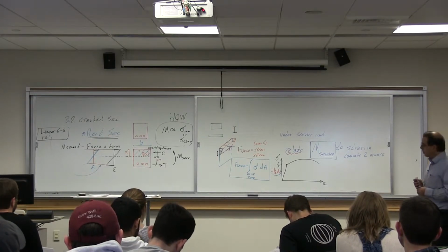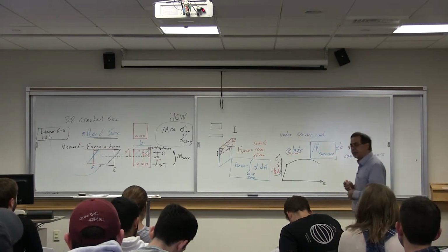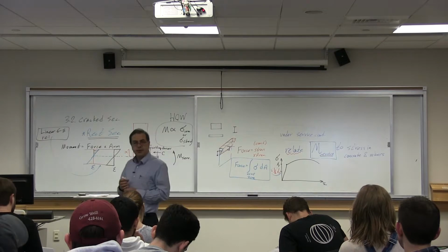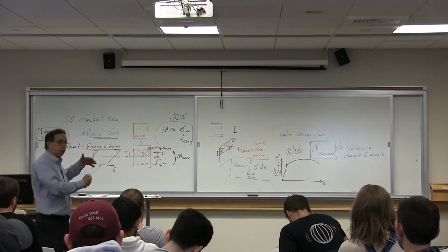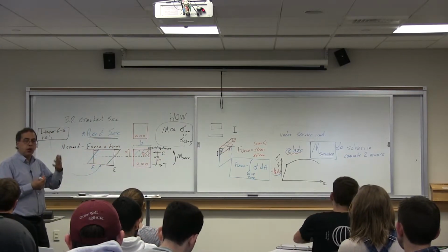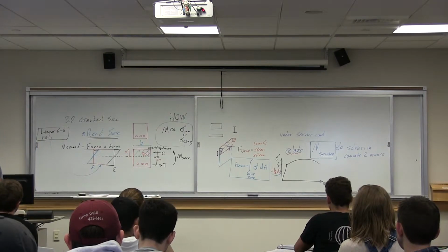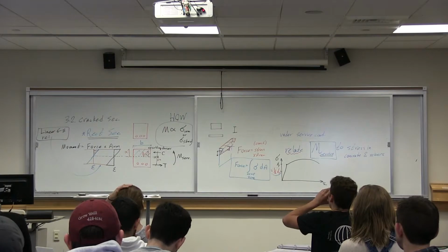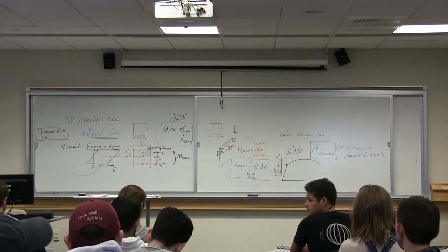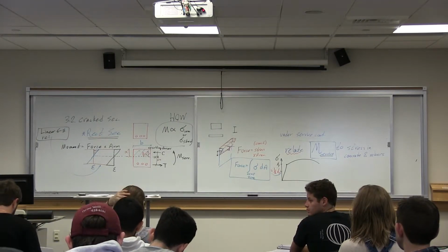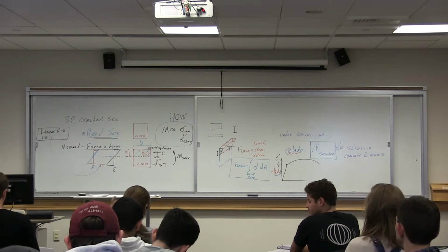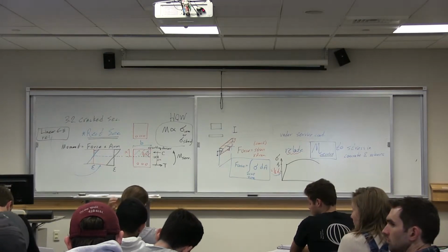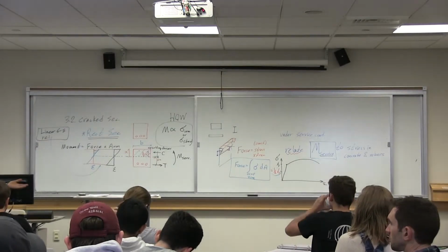First, what's the relationship between the compressive force and tensile force? As you can see, they are opposite and they should be equal. Why should they be equal? They make a force couple. Okay, but why, as a result of that, should they be equal? Otherwise, you don't have equilibrium.